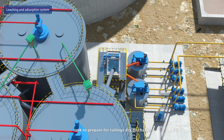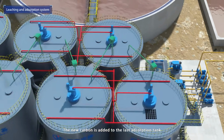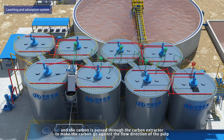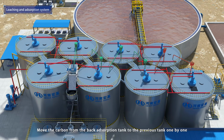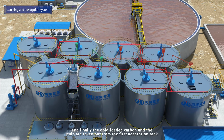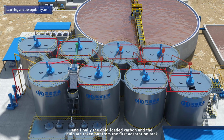tailings dry discharge. The new carbon is added to the last absorption tank, and the carbon is passed through the carbon extractor to make the carbon go against the flow direction of the pulp. Move the carbon from the back absorption tank to the previous tank one by one, and finally the gold-loaded carbon and the pulp are taken out from the first absorption tank.